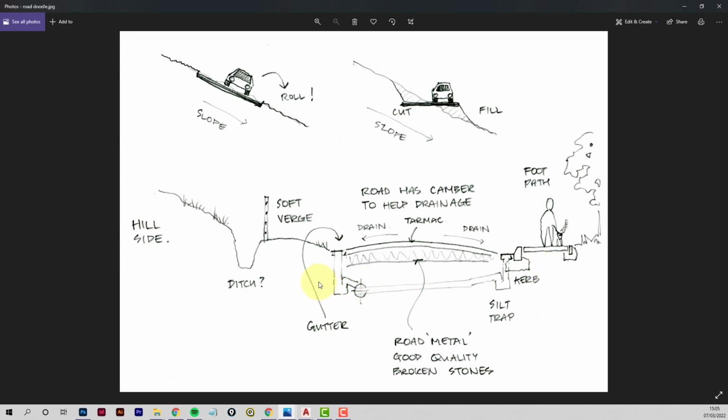In the countryside, it's a bit different. You might have a drain if there's an especially bad bit where it collects a lot of rainwater. Otherwise, it can just be a strip of gravel, or just a little ditch, effectively. Where there's a steeper hill, ditches are really needed, because you don't want that water and the mud to end up on the road, which can easily happen. Okay, in towns as well, you'll find curbs, you'll find proper footpaths, and a curb at the other side of the footpath as well, that usually denotes the boundary. So this is usually where people's gardens start.